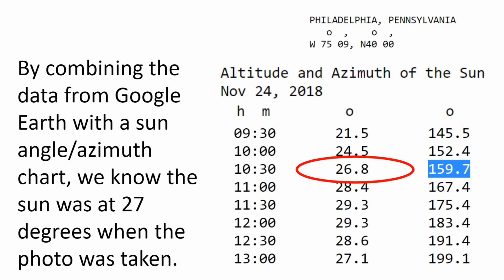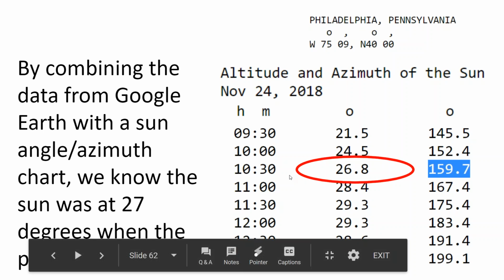And at that point, you can use the same sun angle azimuth chart and PVWatts to say, what time of day is PVWatts telling me my solar array should be turning on? Where is the sun at that time? And where is the tree height? And just use good old-fashioned trigonometry to do your shade analysis. Although if there's lots of trees around, building a 3D model or actually going to site with a tool is more accurate.